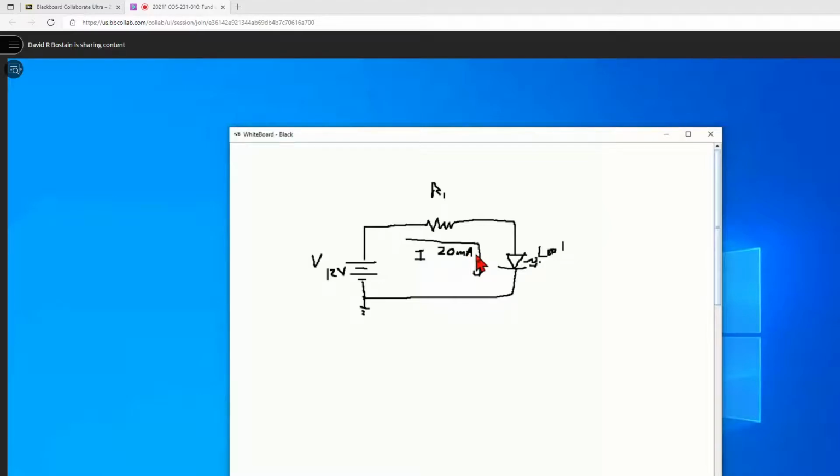Second step, put your hand up if you know what that is. Frank, you look like you got there first. You take the battery voltage and subtract the diode amount, which would be 2.1, and you're left with 9.9. Okay, so we got 2.1. Where'd you get that number from? In the last lesson, you said all light bulbs are going to be 2.1 volts. I said unless I tell you otherwise, and I didn't tell you otherwise, so 2.1 is the right value. 12 minus 2.1, what did you come up with? 9.9. So it's 9.9 volts here, relative to ground.